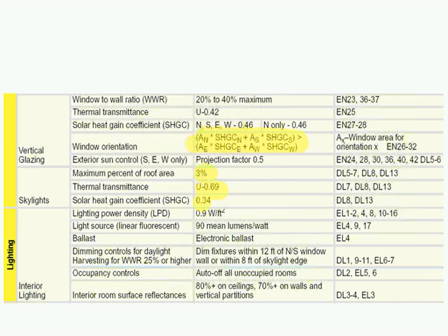Lighting power density, again, there's the 0.9 watts per square foot that we talked about before. 90 mean lumens per watt. Instead of saying high performance T8 lamps, we put in the mean lumens per watt. Standard electronic ballasts, just as an FYI, there's some new electronic ballasts that have come out in the last year and a half. They really weren't out from two manufacturers at the time.